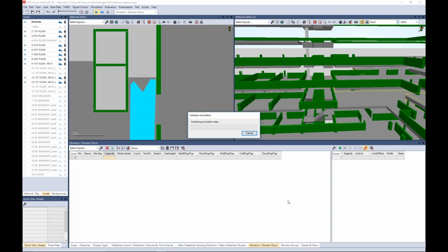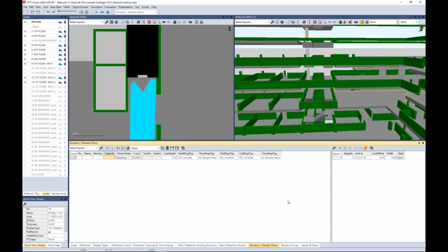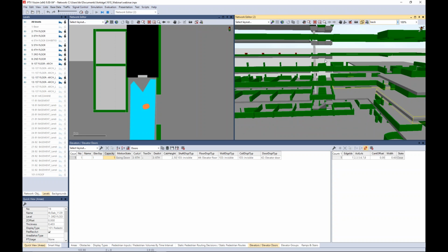So the capacity of an elevator is determined first by its size, by its area content. So when you put at capacity a high number, which is unrealistically high, then pedestrians will always try to get inside, but after some time the doors will close, but only if there's no one standing inside the door blocking it. So a large crowd of people waiting in front of an elevator, making persons being stuck inside the doors, can block an elevator from traveling.